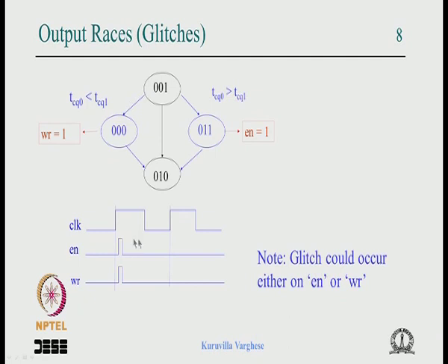If this is used in a synchronous way to enable some muxes and all that, no harm, because the clocking will happen on the next state. But if you use it asynchronously to clock something, then you are in trouble. Say this is a write signal to a memory, then the location can get corrupted depending on the pulse width. Even if the data bus is tri-state, whatever floating values are there will get written into the location.